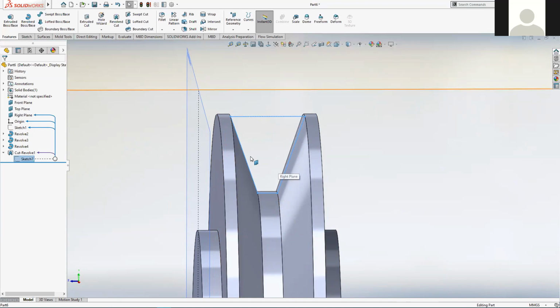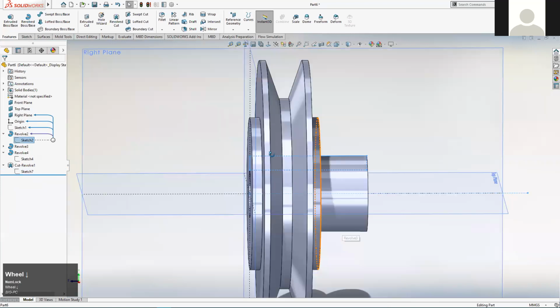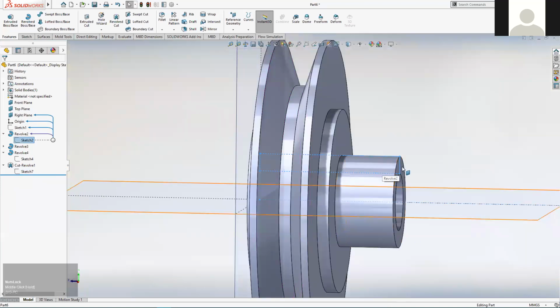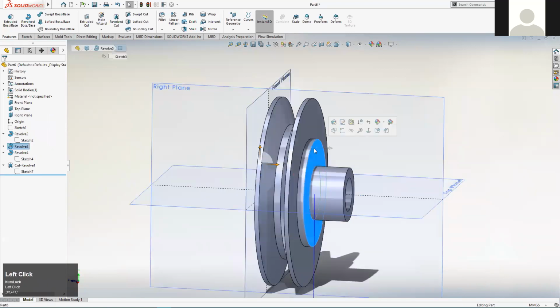V shape there. And likewise, if I was to go in and look at maybe that first feature that I created down here, that initial shaft, I would only be able to view the dimensions that were specific to that shaft section. So that would be a big disadvantage. There would be no one sketch where I could go in and just view everything about this. But the upshot is that this method is more resistant to being changed in the future, or more robust in terms of change.